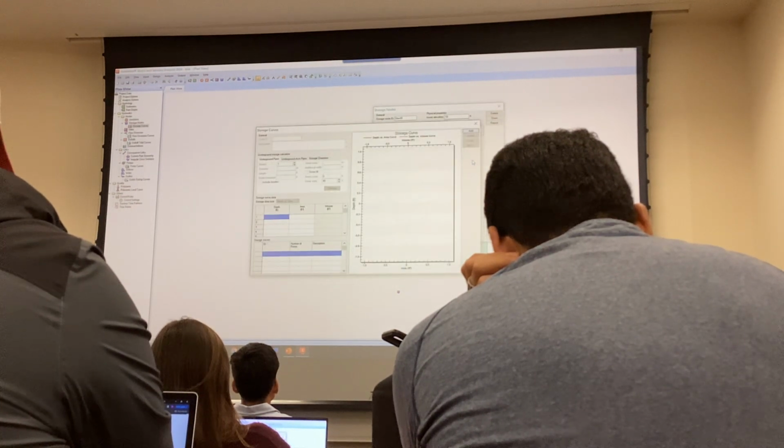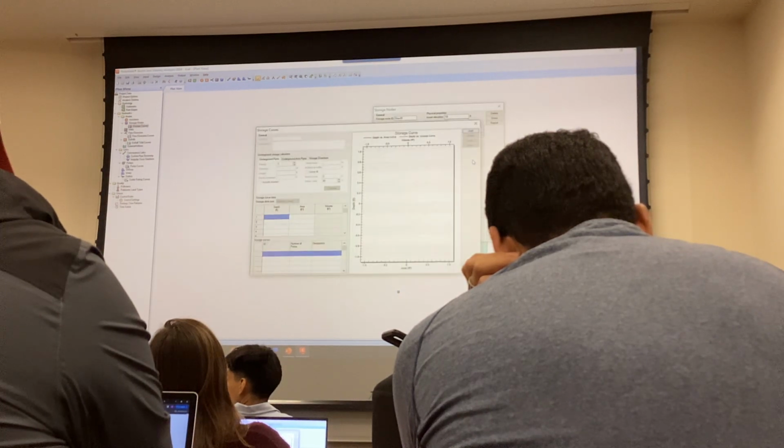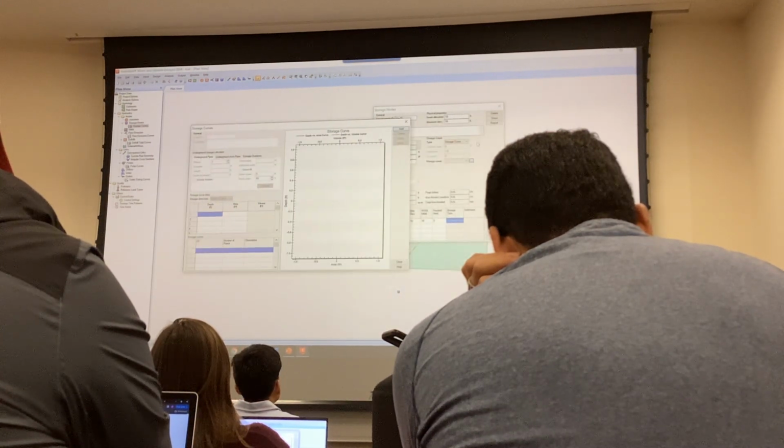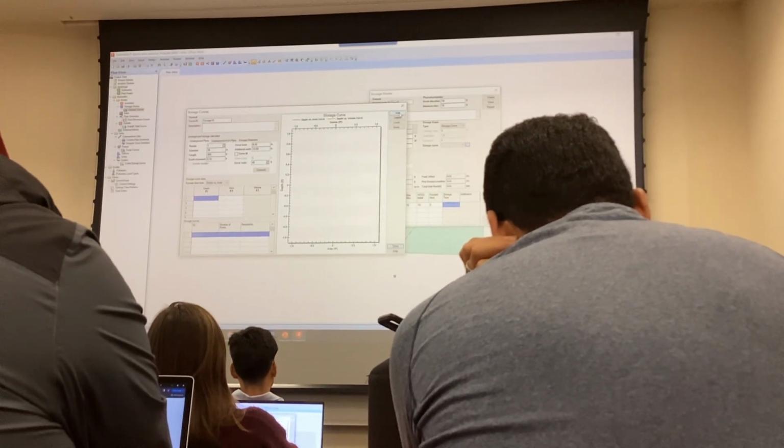Oh yeah, that tree button. Okay, you're correct. I thought the tree button was going to be inside here. So you hit on the tree button. Now you have the option to actually put in the characteristics of your detention basin. You need to hit that because it's the first time you have a detention basin.